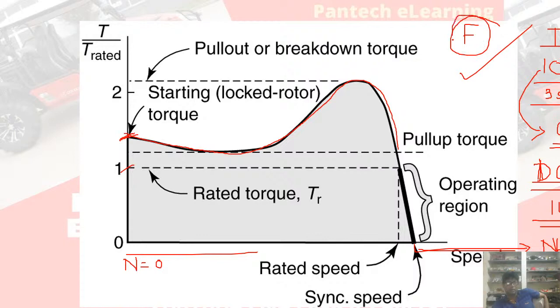That insulation level is not included in this course. So to avoid this hot start and to introduce soft start, a variable frequency drive is required. That means it will never allow the motor to draw that 6 to 7 times current, which is called inrush current, but the machine will be capable of producing the rated torque.